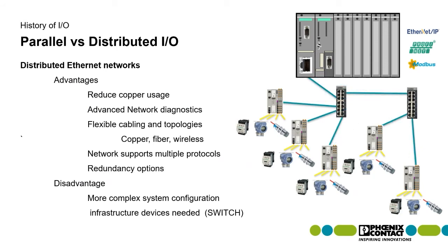So maybe I'll use 2 switches. Maybe I'll do this switch tied to the PLC and these 3 IO cards, and then these 2 IO cards will tie to this switch, and I'll run a cable here behind as my backbone connection. The cool part is I could buy a switch here that says, maybe I'll run 100 meg here. Maybe I'll run a gig here. I'll run a higher speed backplane.